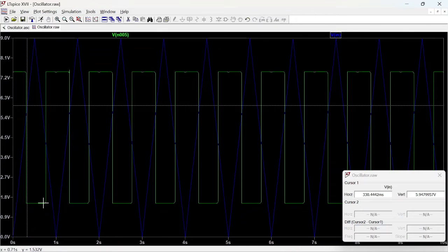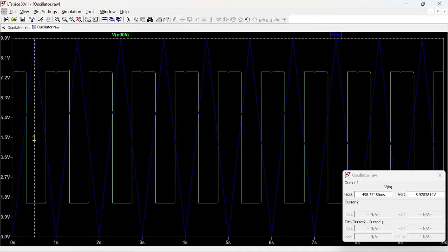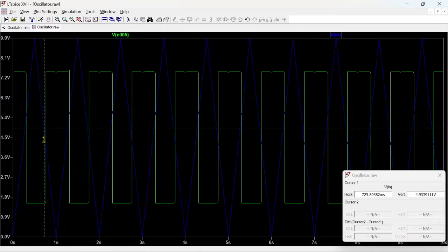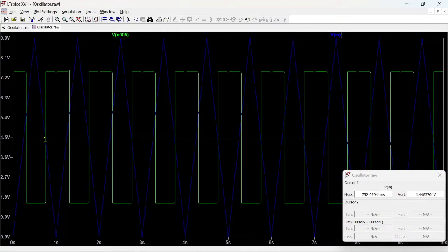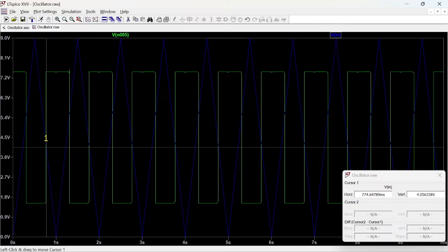It goes down, and then it stays down until our input starts coming back, and when it comes back, the input, this blue one, passes the threshold of 4 or 5, roughly speaking, it jumps up. So if you think about it in the digital world, this would be 0, this would be 1.